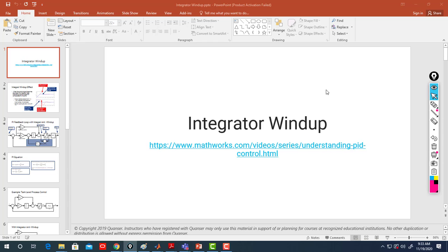This is a cut-off frequency, where you need to make sure that all the high frequency noise is cut off, and the signal that you are interested in remains. You don't cut it. Luckily, in general, the noise is high frequency, and the signal we are interested in is almost a low frequency signal. So that's how we can use a low pass filter to decrease the noise.